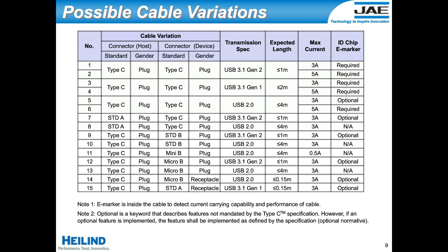Type-C to Type-C cables that support USB 3.1 will have to have at least 22 of the contacts terminated inside the cable. Most people are going to refer to those as full-featured cables. And those can support higher speed USB signals and most of the standard alternate modes as well.